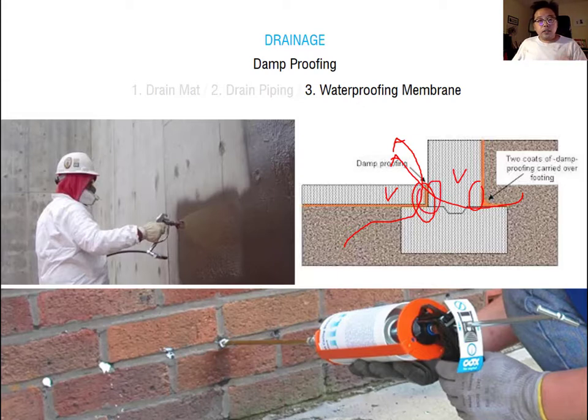So especially you can use some spray. You can see the concrete panel joint here. This joint is usually very narrow. It's hard for water to get in, but moisture passes through. That's why you have to protect against moisture transfer from outside to inside and inside to outside. So this region has to be protected very well. In this case, we usually use the spray over the retaining wall.